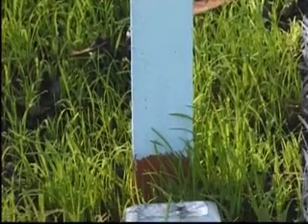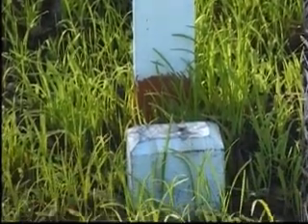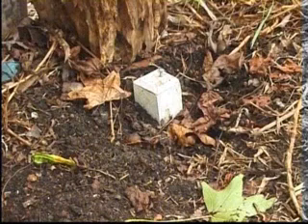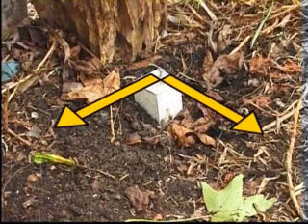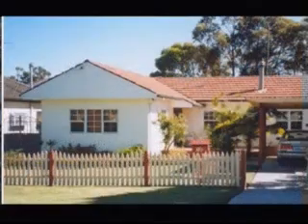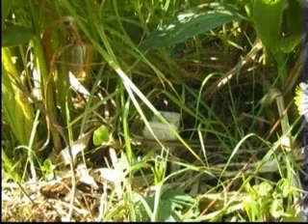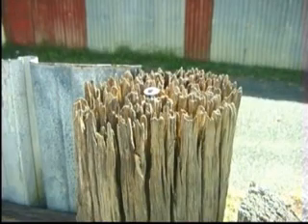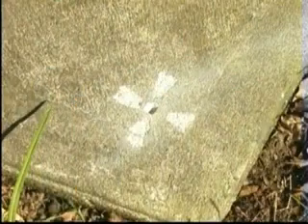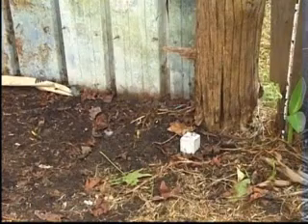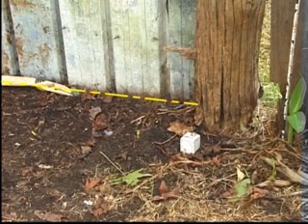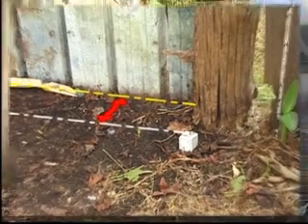On a developed block, a survey mark can be more difficult to locate. It may be a peg, or it could be a nail in a fence post or a mark on a concrete path. It is unsound to use a fence line as a datum from which to start measuring. Fences are not necessarily a true representation of a boundary. With survey marks located, a quick check of actual boundary measurements can be done to make sure they match the dimensions given on the site plan.